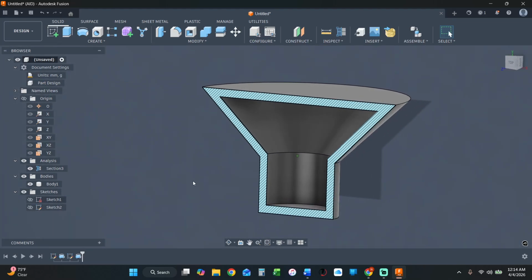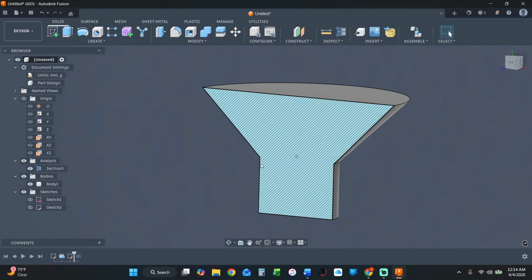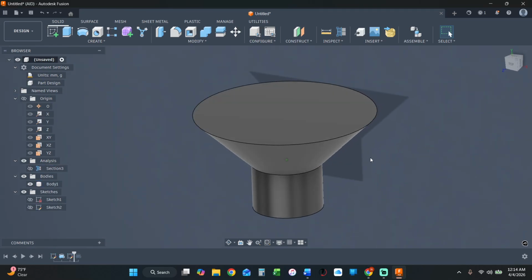So as we get along, we'll show a little bit more, not only of just how to build parts, how to make good sketches, show good practices, but also how to use other parts of your feature tree, which is typically here. And it's kind of split, which is a little unique to Fusion, because you also have your timeline, which, like we spoke about earlier, it just shows everything you've done as you go along. You can go ahead here and you can drag it, so basically you can remove some of the work that you've done. It's not permanent because you can always go roll it back.